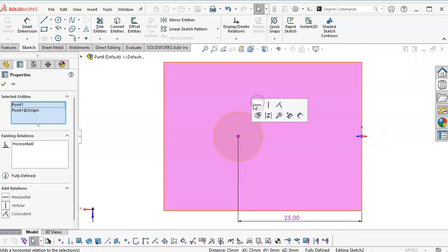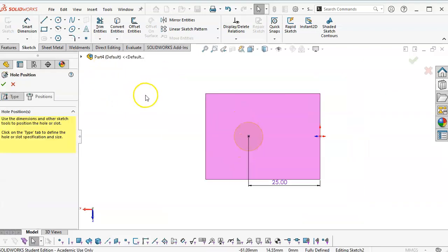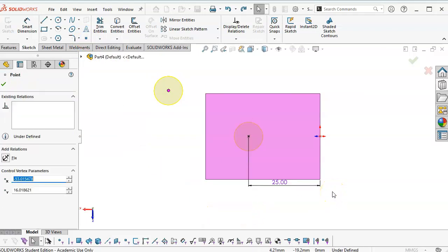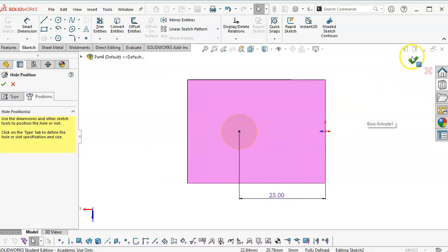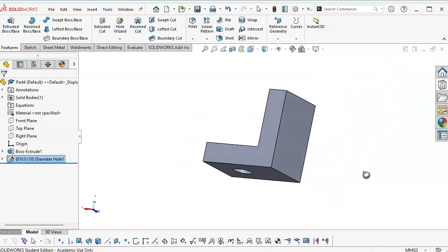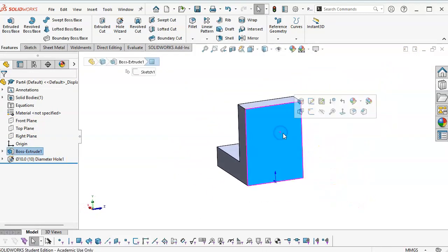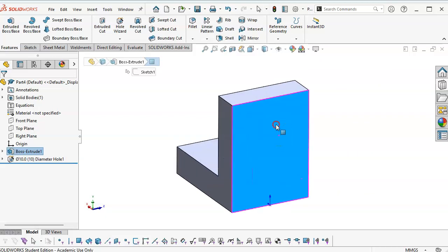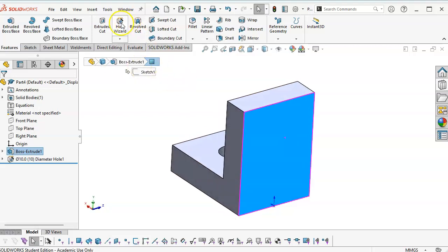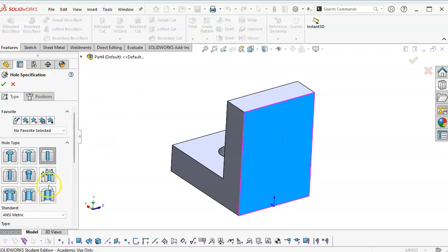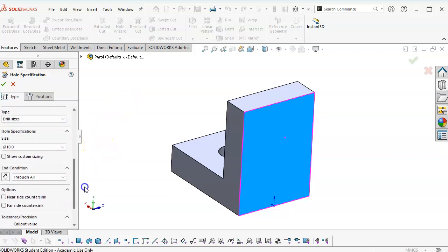Quick mention on the hole wizard: wherever you place a point, you will get a hole. So you pretty much only want to put points where you need them, and that is one of the reasons why we want to pay attention to things like a circular pattern or anything that will involve those, because occasionally it will generate an extra point, which skews the instance count later on. All right, so all of that should be good up to next through all.